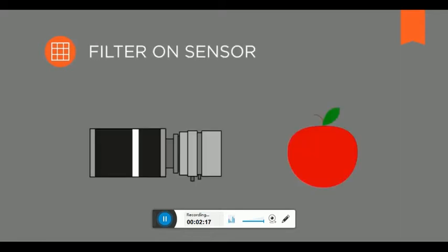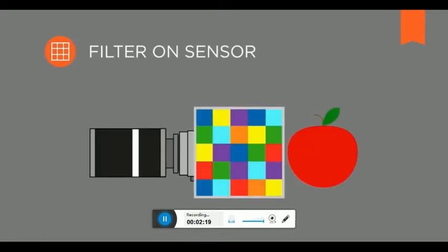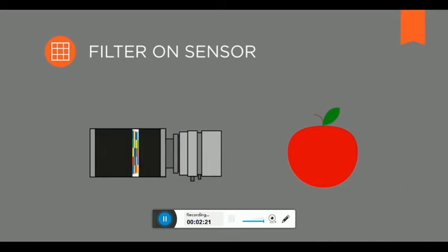Now there are also CMOS sensors with band filters integrated into the sensor's layout. Compared with the other scanning types, cameras with spectral filters on CMOS sensors have no optical parts which require alignment. They can capture objects with different wavelengths in one single shot. These sensors are much more affordable and easier to integrate into a vision system.